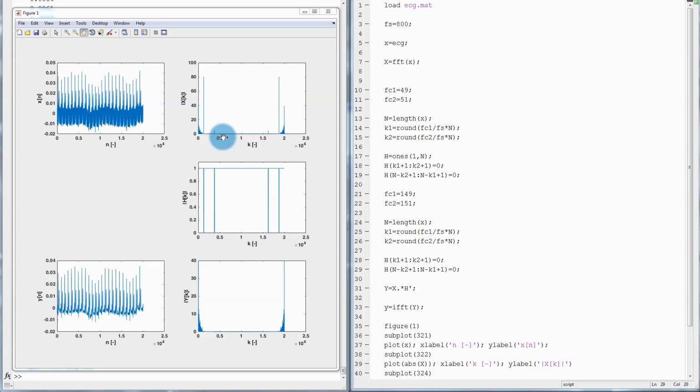In the spectrum, we can have very strong signals and very weak signals. And of course, we would like to see both at the same time. So to allow us to see this, we oftentimes use a logarithmic scale for the vertical axis. So in MATLAB, instead of plot, you can use semilogy, which will give a logarithmic scale on the vertical axis.